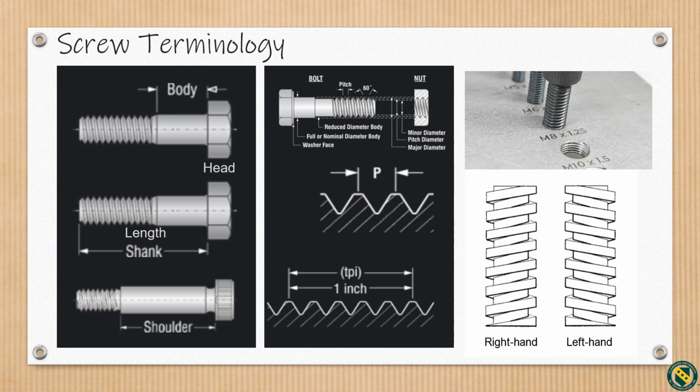The length of a headed fastener is the distance from the intersection of the largest diameter of the head with the bearing surface to the extreme point, measured in a line parallel to the axis of the fastener. The grip length is the total distance between the underside of the nut or bearing face to the bolt head. This includes the washer and gasket thickness. A screw thread is the ridge of uniform section in the form of a helix on the external or internal surface of a cylinder. An external thread is threaded on the outside of the cylindrical piece of stock, and an internal thread is threaded on the inside of a cylindrical hole.